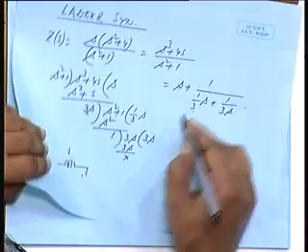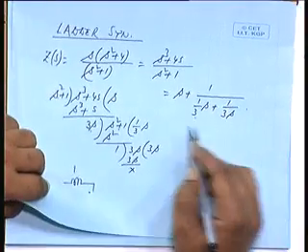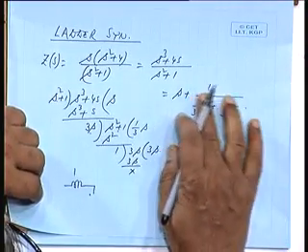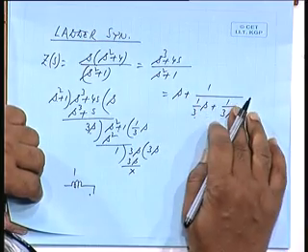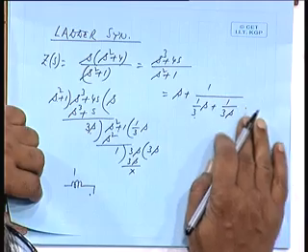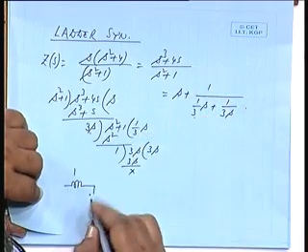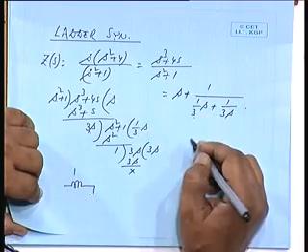So, it will be like this. So, this is an impedance. So, this whole thing is an admittance, 1 by an impedance, is it not? So, this is an admittance, the first element I have realized by 1/3 s. 1/3 s is the admittance of how much? 1/3 farad, Cs is the admittance, so 1/3 farad.